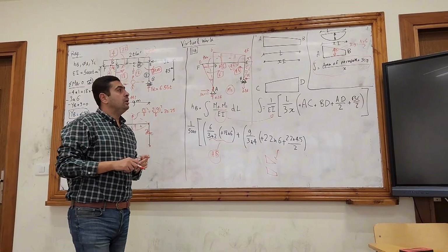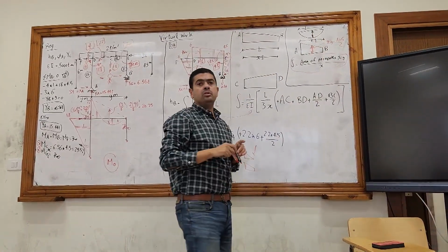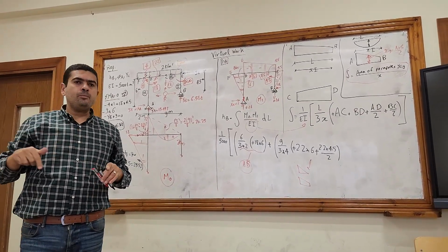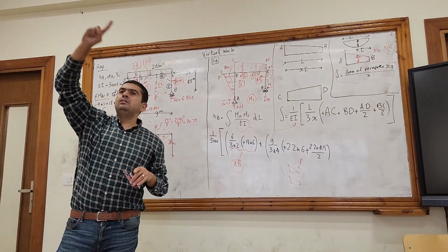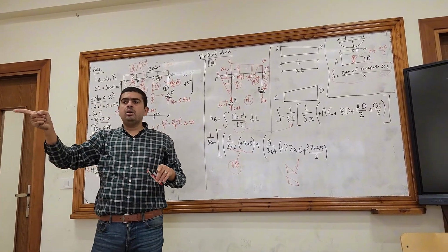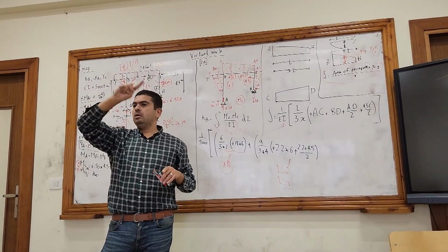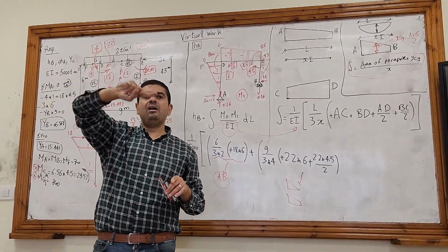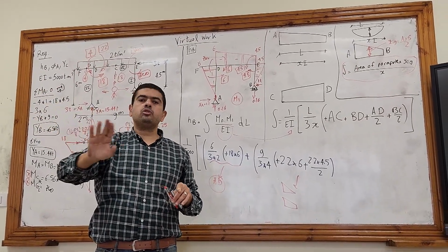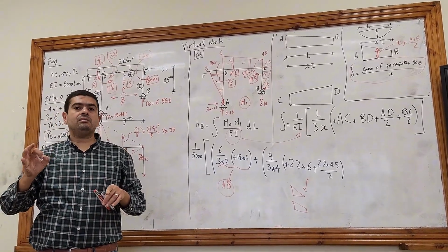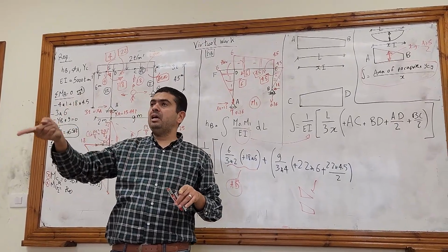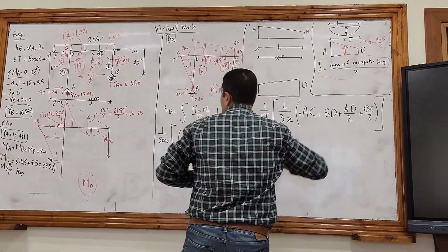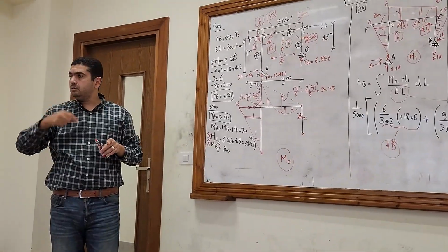What will the sign depend on? Is the parabola downward or upward? Downward or upward doesn't refer to the direction of the data; it means, is it subtracted or added? Is there a bending moment diagram which will have this shape? All the curves are downwards, right? When will I see a curve that has an upward arch? It's the only case in which I will see a bending moment diagram that has an added curve, okay? So for now, this curve is downwards because it's subtracted.